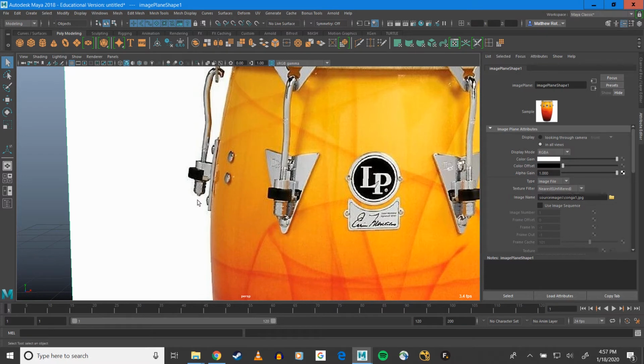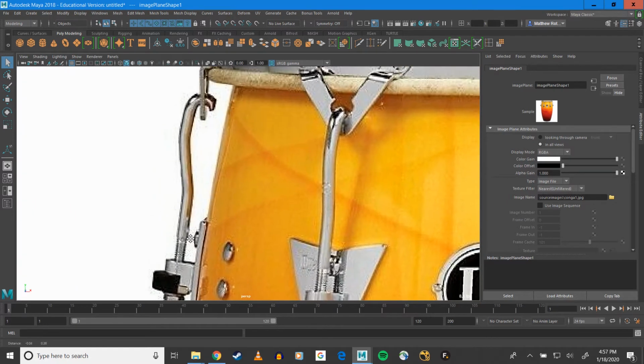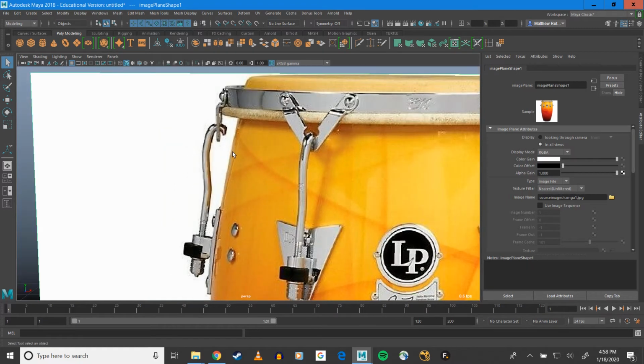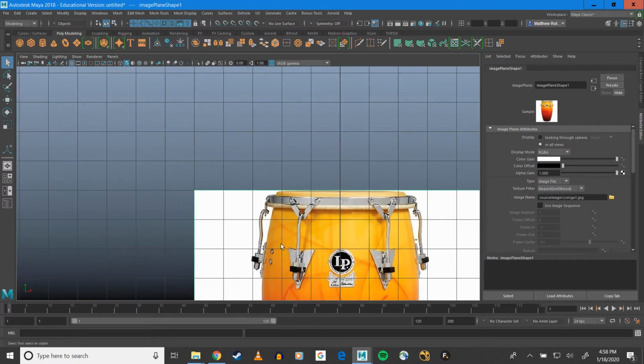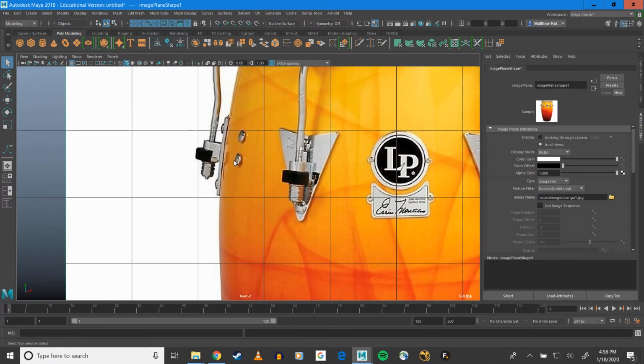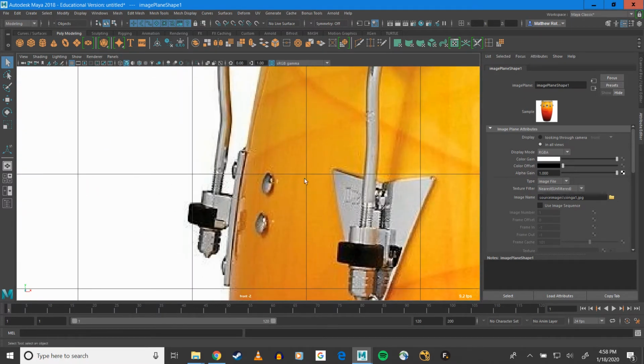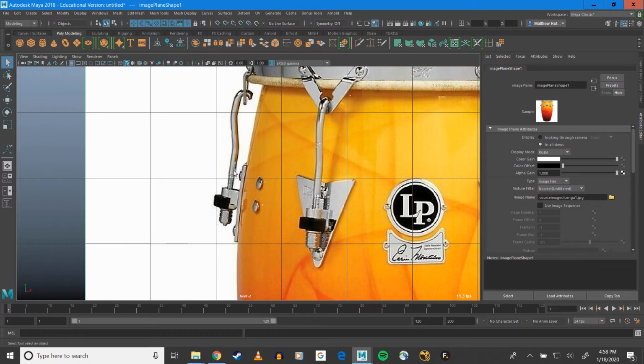Then you would extrude that poly geometry along a curve like so, the same way I do in my extrude polygon geometry along a curve tutorial. But just to give a little highlight on lofting using nothing but curves, I just want to pay a little attention to that right now.